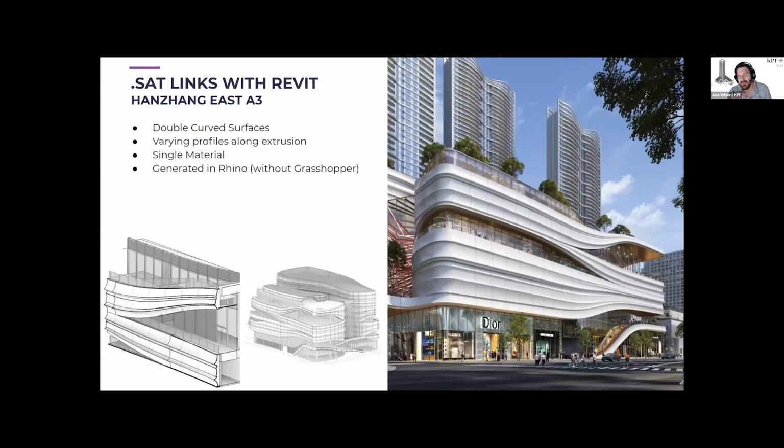So there were a number of iterations of paneling that was just sliced up in Rhino itself, and then a 3D AutoCAD file was brought into Revit to allow the joints to be displayed in elevation and 3D. This just massively increased performance rather than slicing up all of the geometry itself. One thing I believe we've also done when bringing in SAT is that we always bring it inside of a generic model. So that allows it to cut perfectly. This is something we have learned while doing one of the multiple curtain wall panel situations and playing with the Rhino geometry over the years.